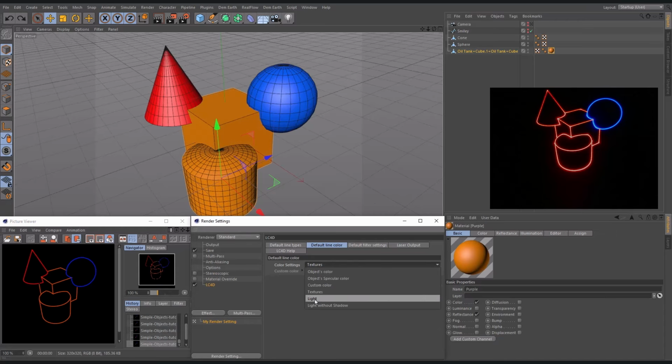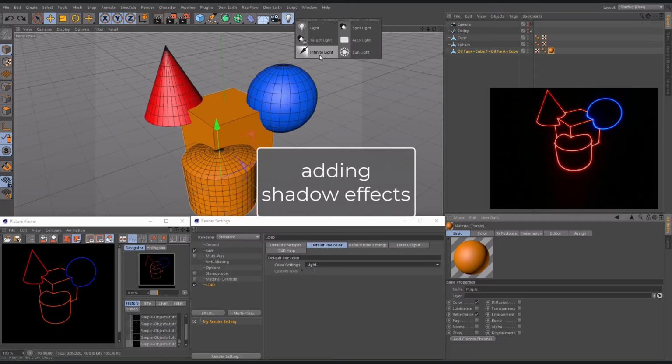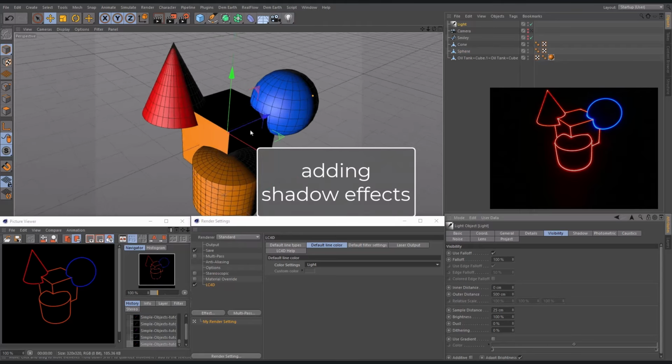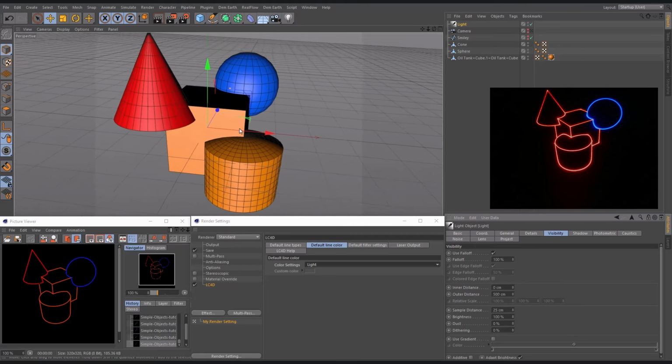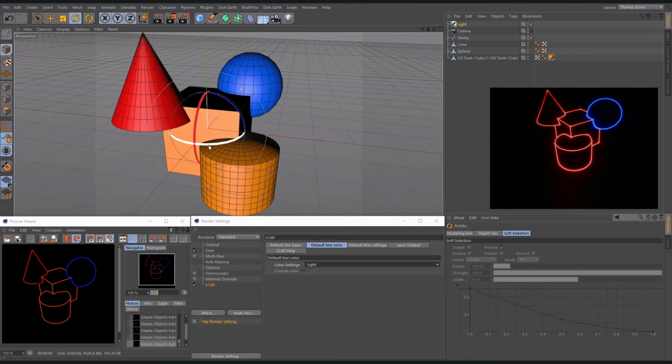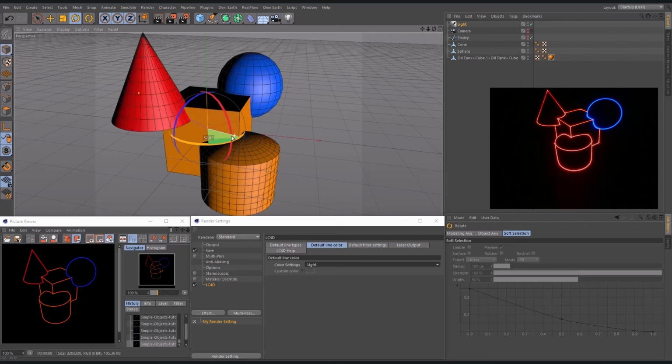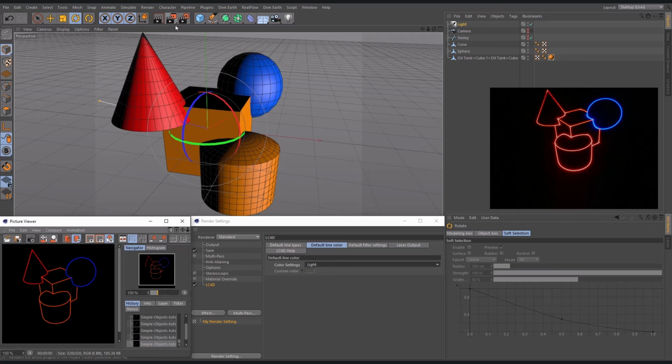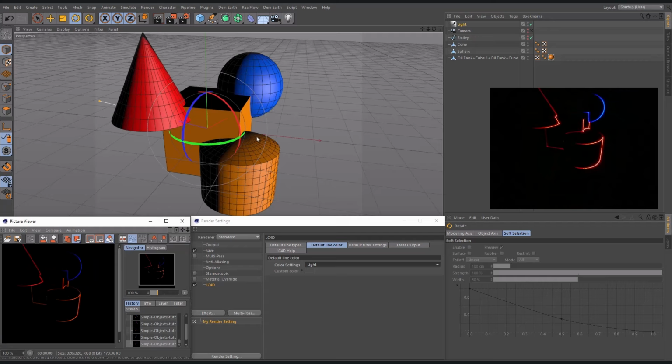Another very interesting function will be the colorization by scene light objects. This means that the whole scene output color is influenced by the scene light objects and the resulting shadowing effects. So let's slightly adapt a light to our scene and adjust the spot angle so that we will see some nice shadows as well. And after rendering, you can see that the previous light settings are now directly calculated into the rendered laser frame, as well by adding very nice soft lines and fadings.